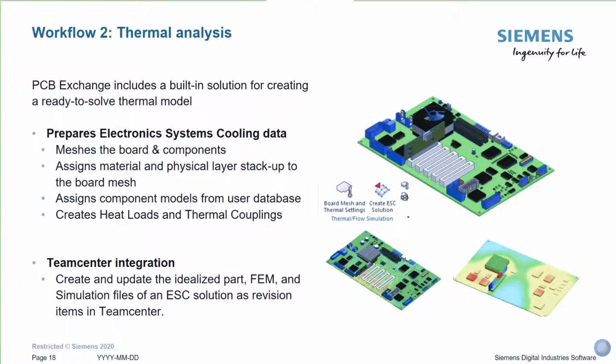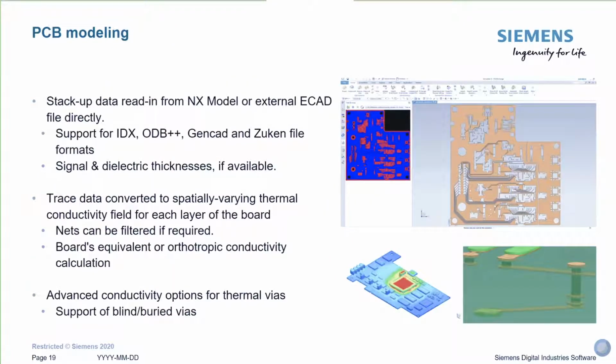We'll get to this a little later in the presentation, but if you make changes on the CAD side by moving components, or by importing or moving components from the electrical domain, you can push those changes with the CAD CAE associativity to your finite element model and simulation files without having to redo your simulation all the time.